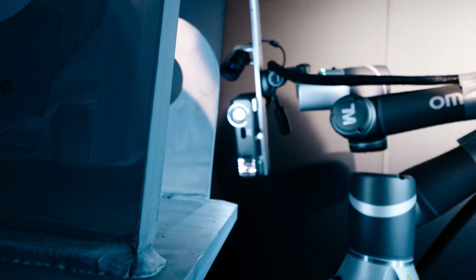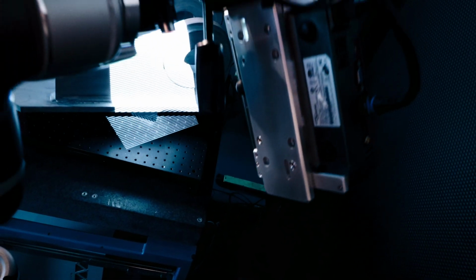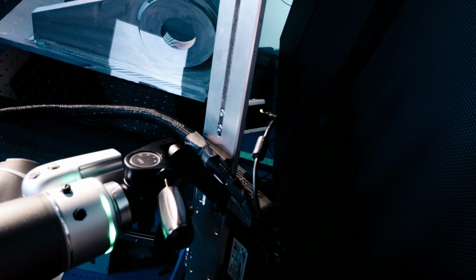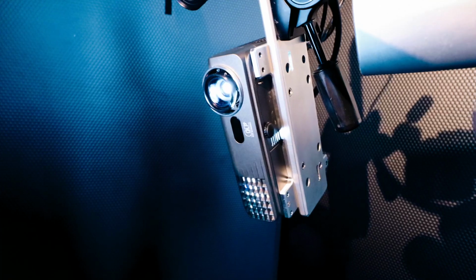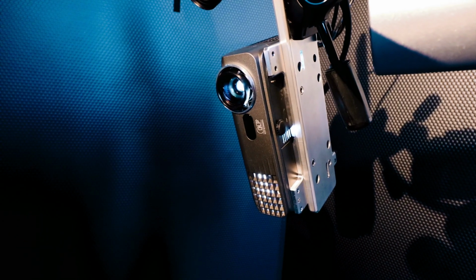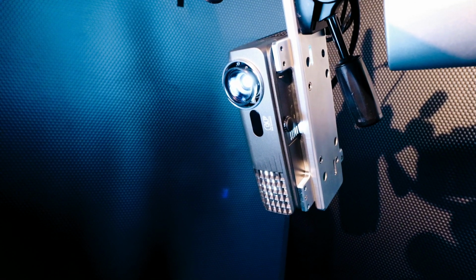As you can see, the robot is taking different positions along with the positioner rotating so that it can capture all angles of the part. As the software continues to scan the part, it will begin to align itself to previous scans. In the end, we will have one mesh file that can later be exported as an STL that can then be used within the PolyWorks environment.